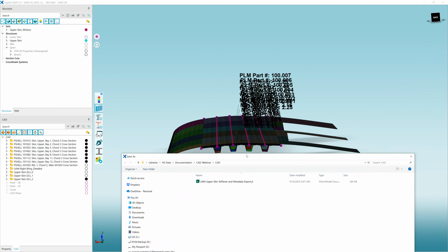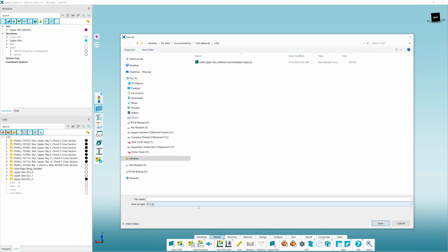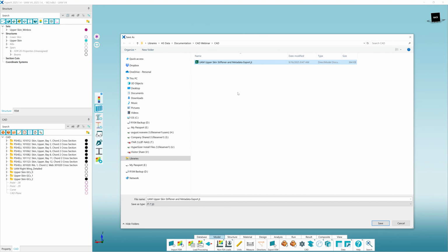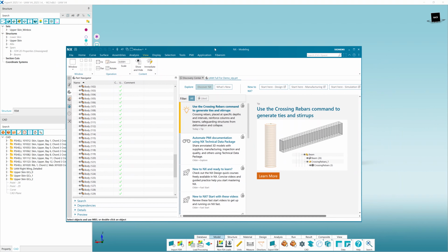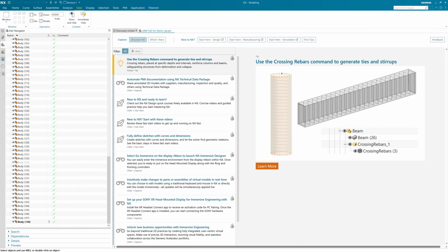If you wanted just the geometry, you could use pretty much any format you'd like. And I should mention this STEP format also supports the metadata that I've added. So I'm exporting that file, and now we'll hop over to NX CAD and just briefly look at what that generated CAD file looks like on the receiving end.